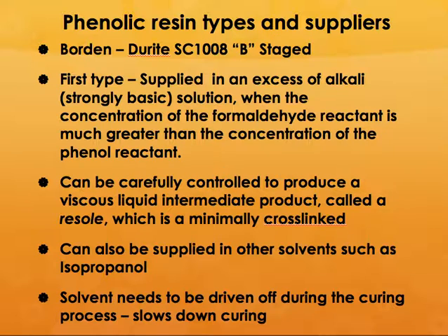So the first kind is usually supplied in a solvent such as isopropanol, or not usually acetone, but isopropanol. But even this isopropanol is not the best material for handling. So you can't let yourself or your technicians be exposed to this material, but you need to drive off this solvent during the curing process, which can slow down the curing reaction.